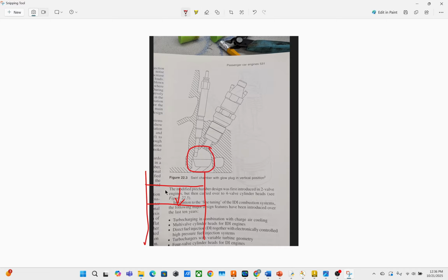And because you don't have the bowl, you therefore have the design freedom to put in cutouts in the piston so that your valves have room to travel down farther than they're supposed to if it should occur. If your timing belt breaks, for example, and the valves are in the wrong place when the piston comes up, it doesn't damage the valves or the piston.